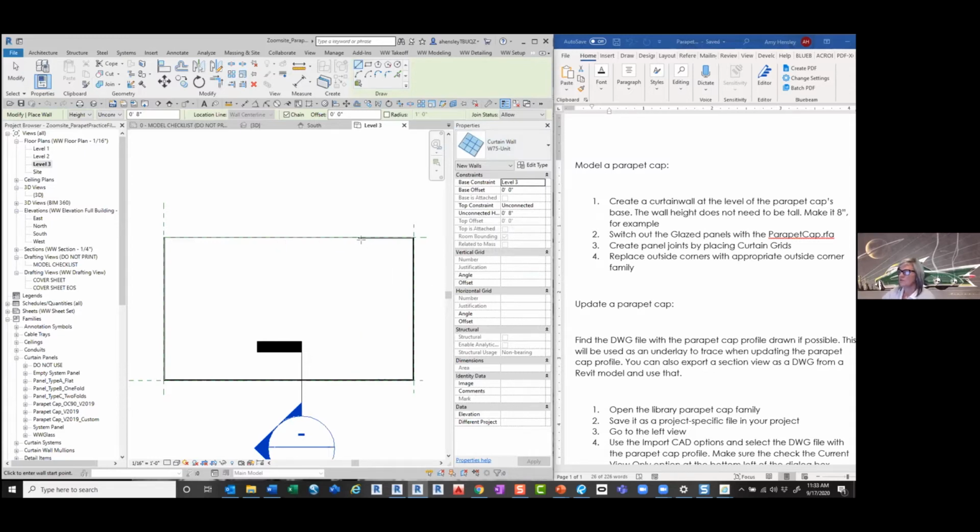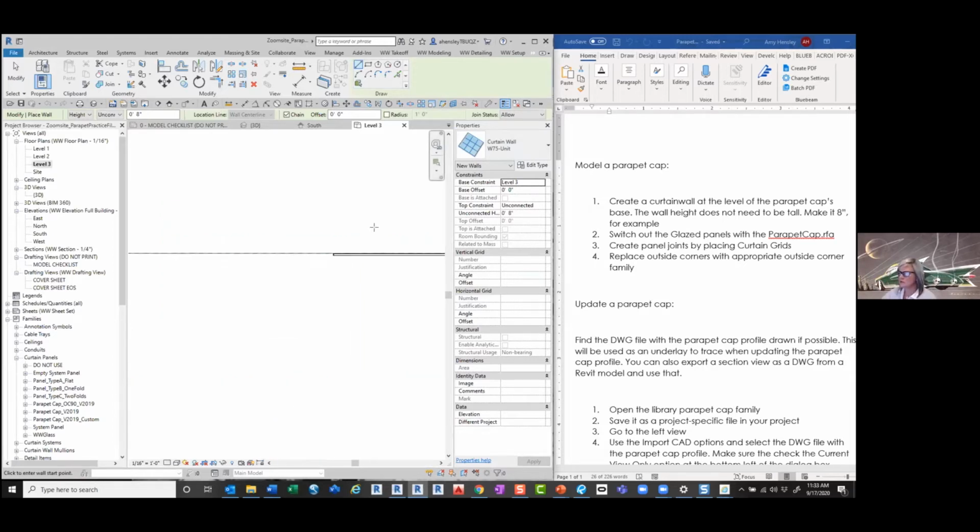So when we're building these walls, just like with anything in Revit, you want to work in the right direction. So we're going to go clockwise around the top of this wall, starting just at this back corner here. I'm just going to pick right on this little corner. We're not being super critical about joints and things at this point. This is the concept of placing a wall and putting in the caps. So I'm going to pick on that point.